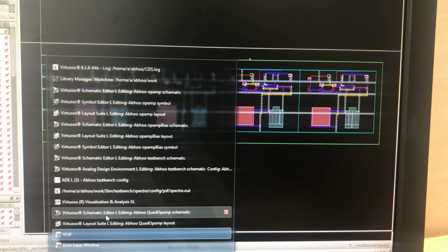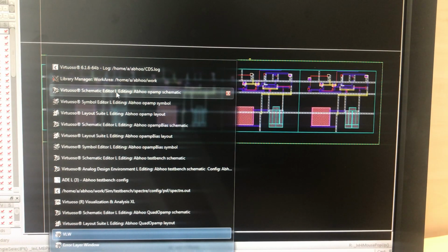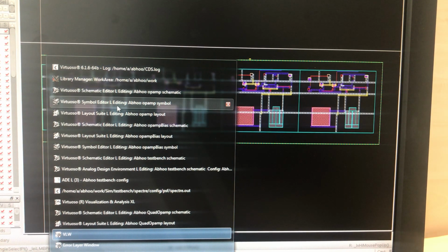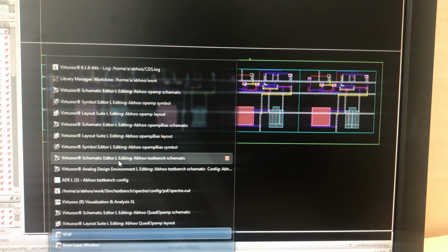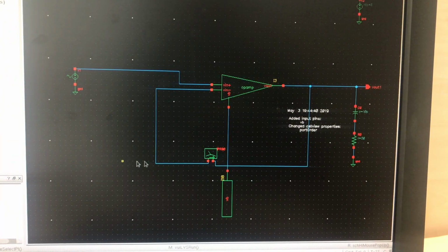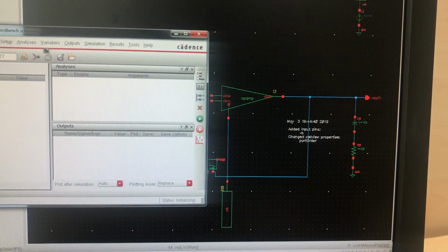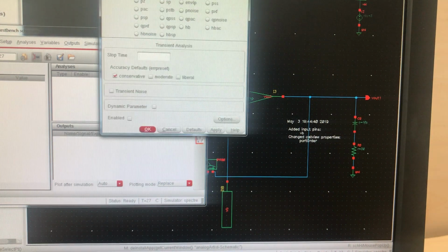And then after that, we went for the post layout analysis. In this case, I will demonstrate 2 post layout analyses. I already have a test bench. So the first one, we'll do the stability analysis. So I put a probe, iProbe, in a feedback loop, and you run the analysis. You choose to run STB.